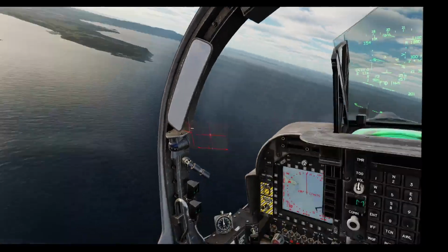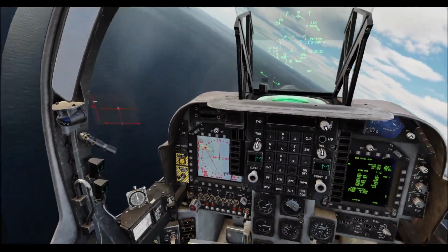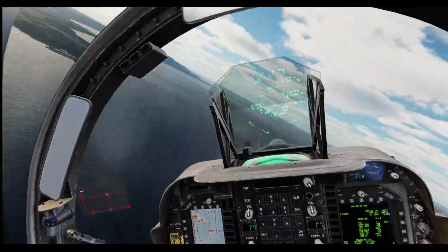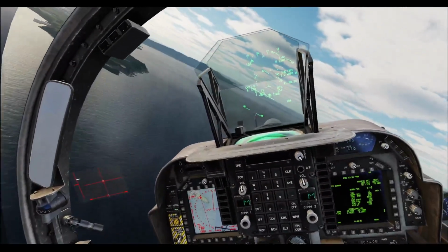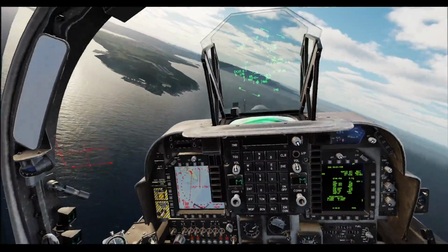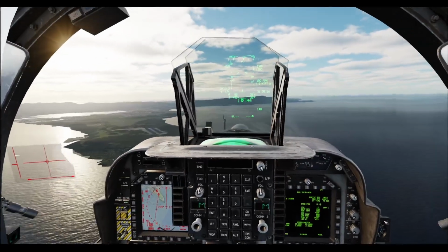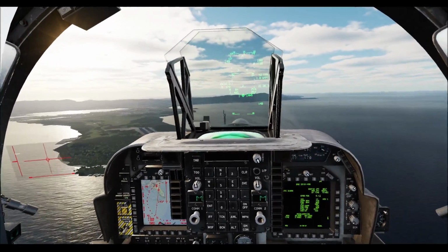And we're going to go straight and level just now, and I'm going to bring the scale up. There we go, so a little bit wide. So we're just going to point the nose in. 1.2, a little bit wide, let's point the nose in. Okay, bring the power back, there's my landing, my DHLA.